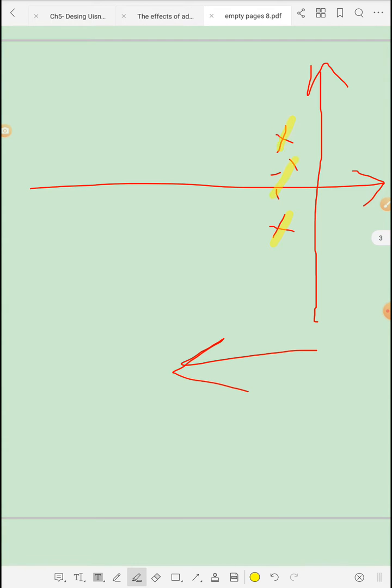So in order to satisfy the dominance of those closed loop poles, the remaining poles of the transfer function, or the roots of the characteristic equation, should be far away.